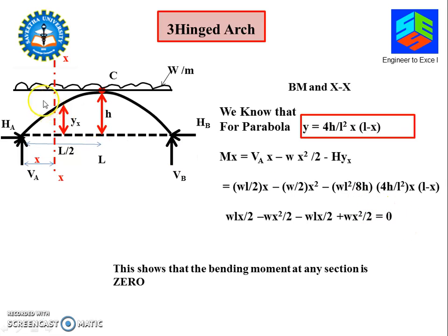Fantastic. It means that when an arch is loaded with a completely UDL, your bending moment at any point will be 0. You will have 0 bending moment. See how powerful the arch is.